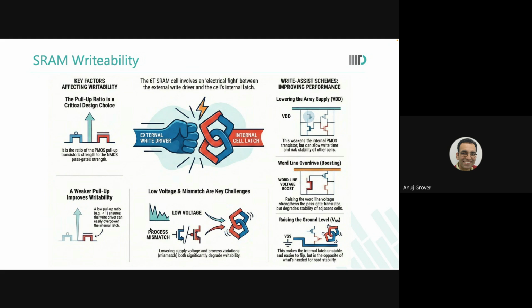Yes. So his question is about the negative bitline voltage you mentioned: we first discharge to 0 and then go beyond. Yes. Now that is a design complexity, but we are okay with design complexity. Look at how we converted that 14 transistor D latch into 6 and said we will take care of the read margin, write margin, and so many figures of merit. We are agreeable to take care of them. Why? Because area is diamond. Because I can make my memory cell denser by using this kind of write assist technique, I'm ready to add more design complexity in my system.